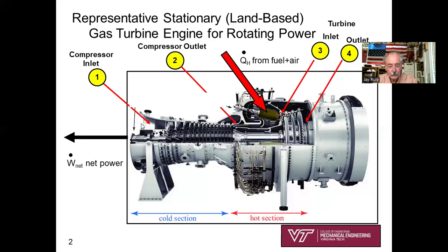So I showed the air coming in. And here's the exhaust gas going out from here. So open system, operating steadily. Just from the picture you're looking at, this is different than an internal combustion engine that we just covered, where our thermodynamic model is for a closed system. Our model for this piece of equipment is going to be a steady state, steady flow, open system, operating in a cycle, with these multiple components.